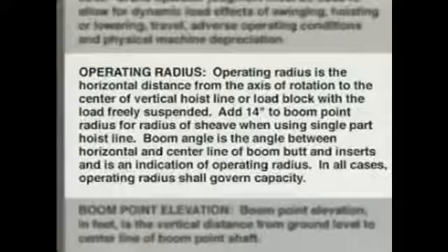The machine equipment section provides a more detailed accounting of the crane's equipment. For example, here we see that the crane's total counterweight of 122,400 pounds consists of 3 separate counterweights that range from 39,000 pounds to nearly 42,000 pounds. The chart instructions for reeving the main load block must be followed to ensure that the proper number of line parts are used. Each maximum load value listed on the chart should be greater than or equal to the maximum capacity that will be required for the lift.